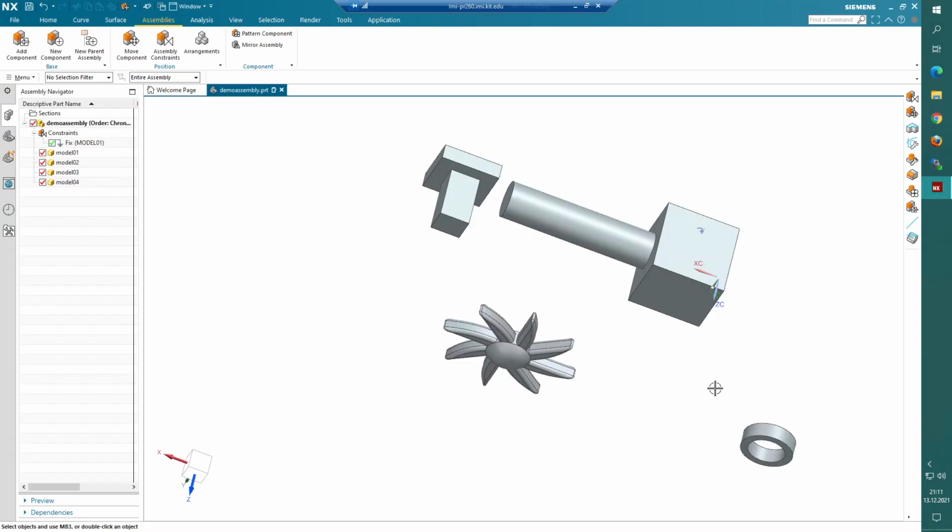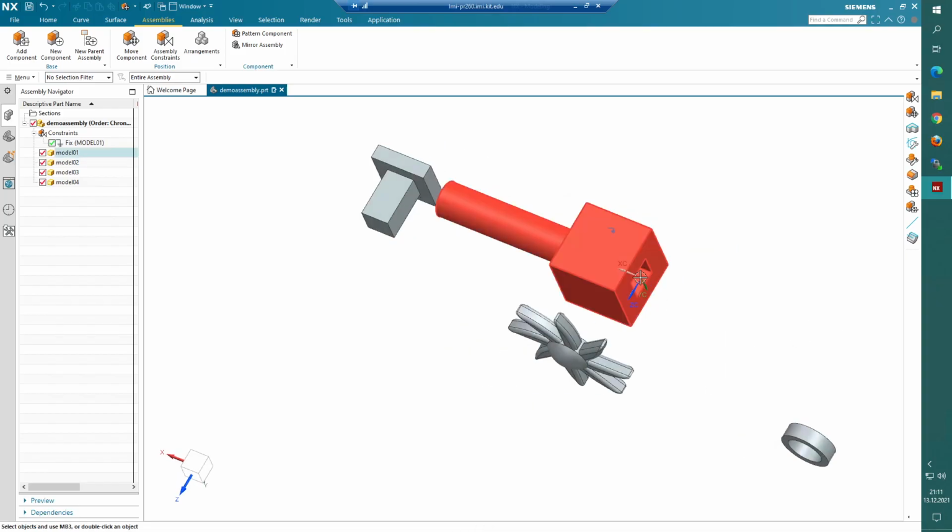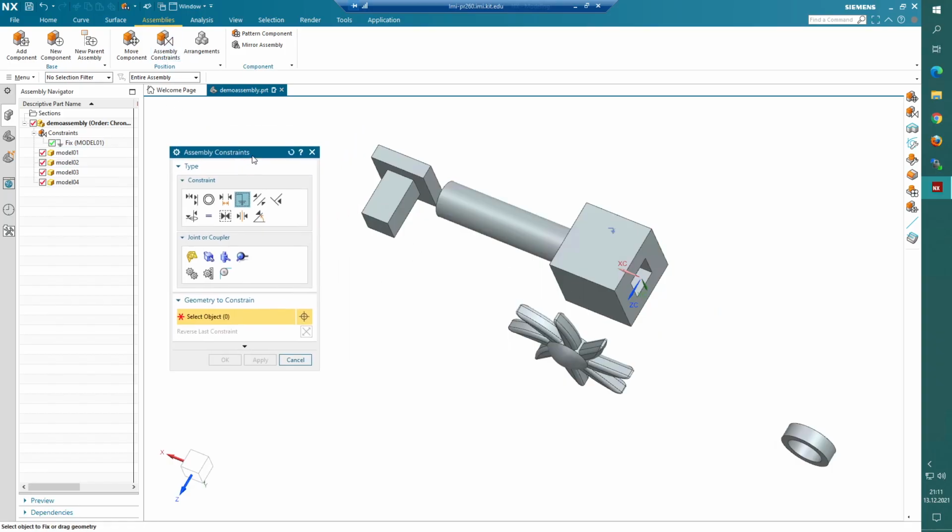And now basically in the end, our goal is that everything's only movable as intended. And this thing shouldn't be movable at all. It should just stick in here and stay there. So to do that, we can use one of these constraints right here. And I'd say the best one is that, touch align. And here you have multiple functions. I think usually it's on find closest, and I think you can leave it on that.